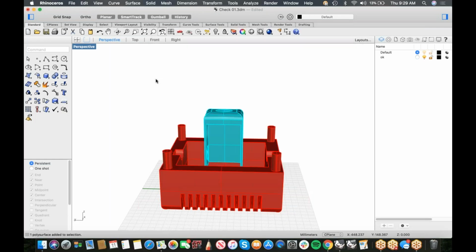If it's just going from Rhino to a printer, you're fine. If it's going from Rhino to a CNC machine, you're fine. All right, but if it's going to a solids package, you need to understand what the tolerance of the inputting package is going to be in order to have this transfer successfully. Otherwise, they'll kick it back and say, this is not a closed model. And you're like, it is. I'm looking at it in Rhino and it's closed. And they're going to say, well, it's not closed here. Well, that's because your tolerances are not high enough.